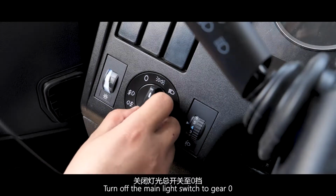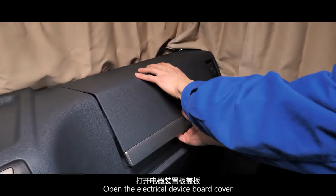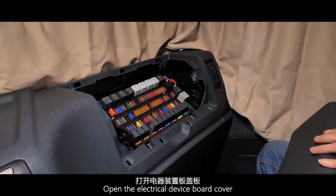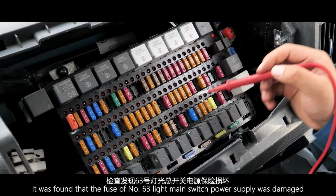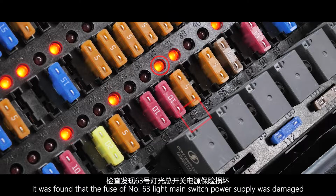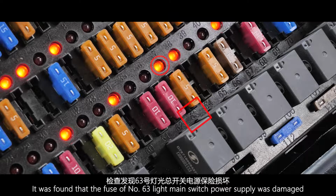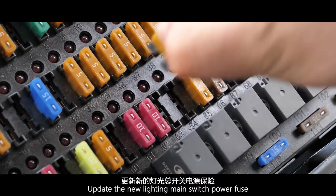Turn off the main light switch to gear 0. Open the electrical device board cover. Main lighting switch power fuse position. It was found that the number 63 fuse, the light main switch power supply, was damaged. Update the new lighting main switch power fuse.